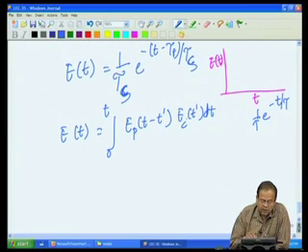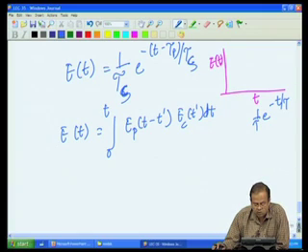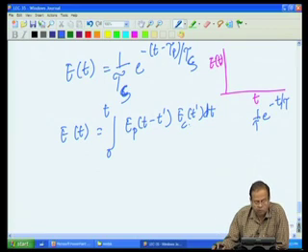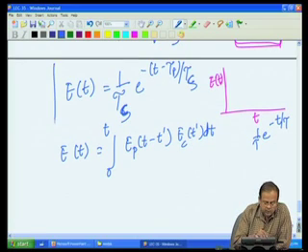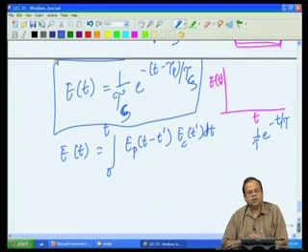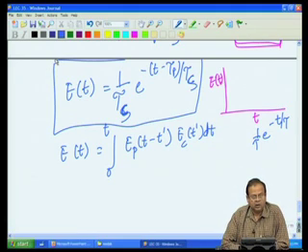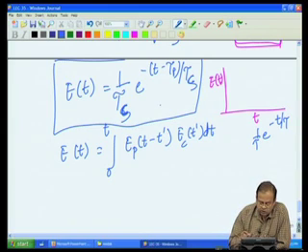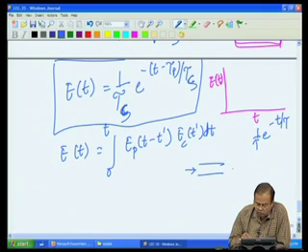So, if we take the appropriate values for single plug flow and single stirred tank and put them together, we will get the exit age distribution, which looks exactly like this. This is the situation, just to refresh ourselves: we had a plug flow reactor followed by a stirred tank reactor.